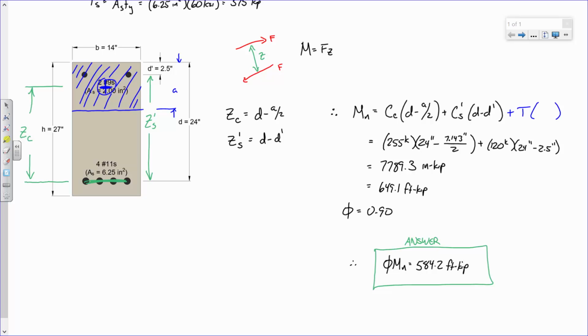But how far is it from the tensile force to itself if we're summing moments? It's 0. It's like when you're solving reactions in a beam: you sum the moments at A to determine the reactions at B. It's not that you're not considering it, it's that you're summing moments at one particular location to eliminate that variable.